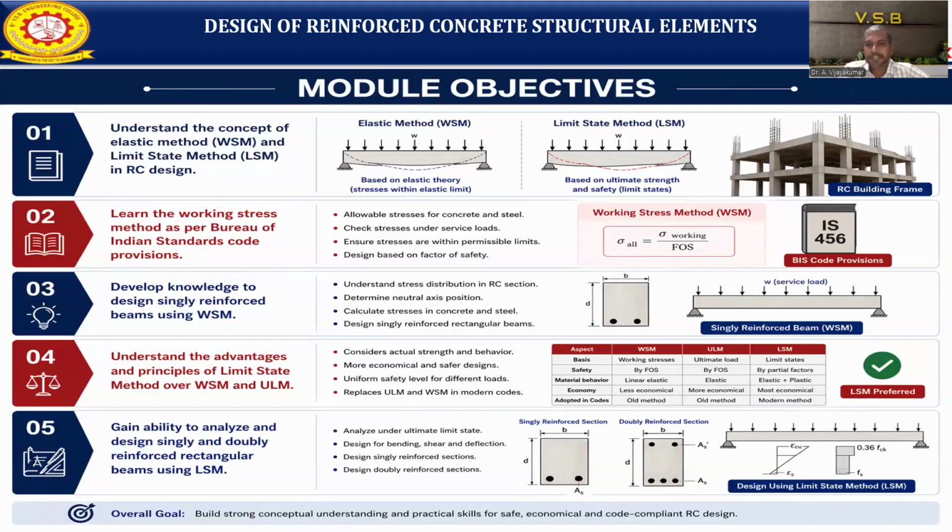Now, to ensure the stresses are everything within the permissible limit. When you're calculating the stresses, all the stresses need to be within the permissible limit. The limit value is given by IS 456:2000. Okay, that coefficient we need to check for the design of the structural members.